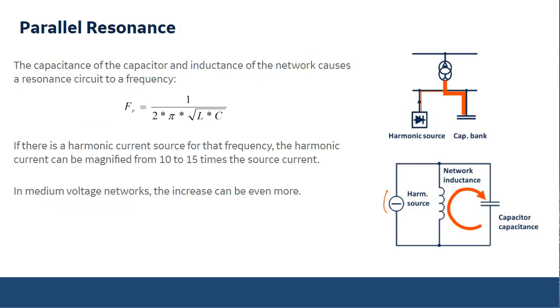There are two ways what kind of resonance you can have in there. Typically your network and your transformer and everything, they are inductive. You have the transformer in there and it has the secondary winding which is inductive. Now when you add your capacitor there, if you don't have any reactors in front of it, you will have a resonant circuit.